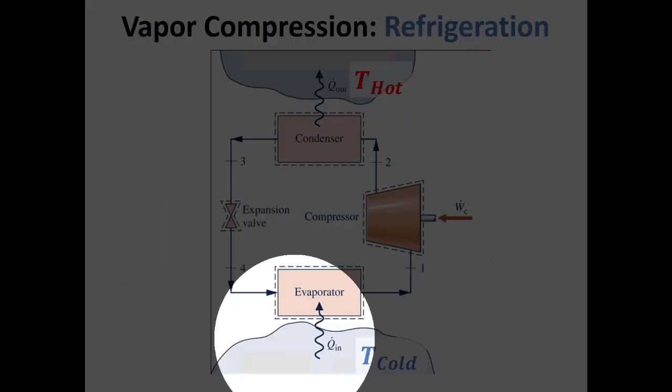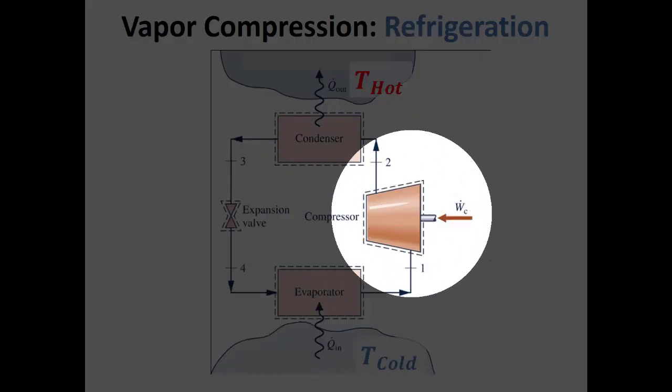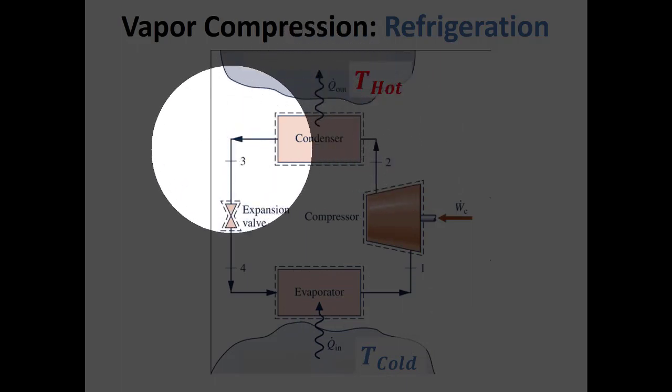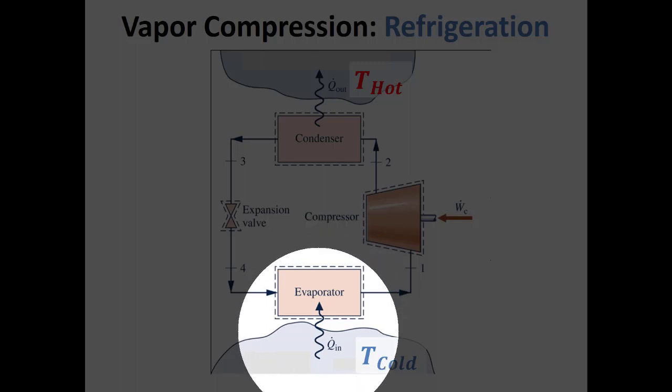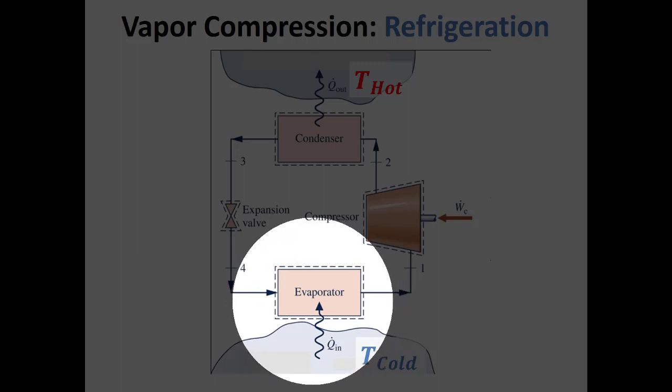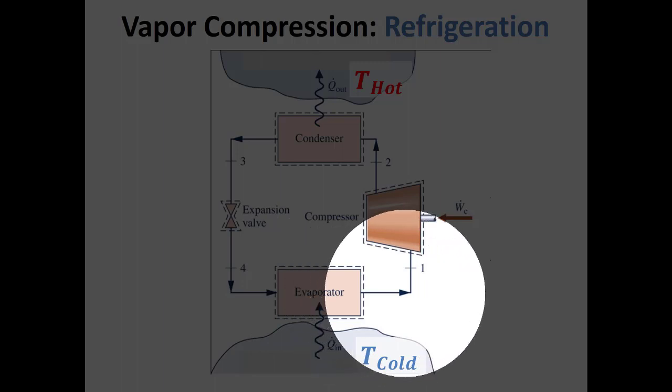On our cold side, we have an evaporator, because now our working fluid, it's not water, but it's something like water in that it's moving back and forth across a vapor dome. Instead, it's some refrigerant. Now, this refrigerant evaporates at a temperature that's colder than our cold space. So it can accept heat from our cold space, and that evaporates our material.